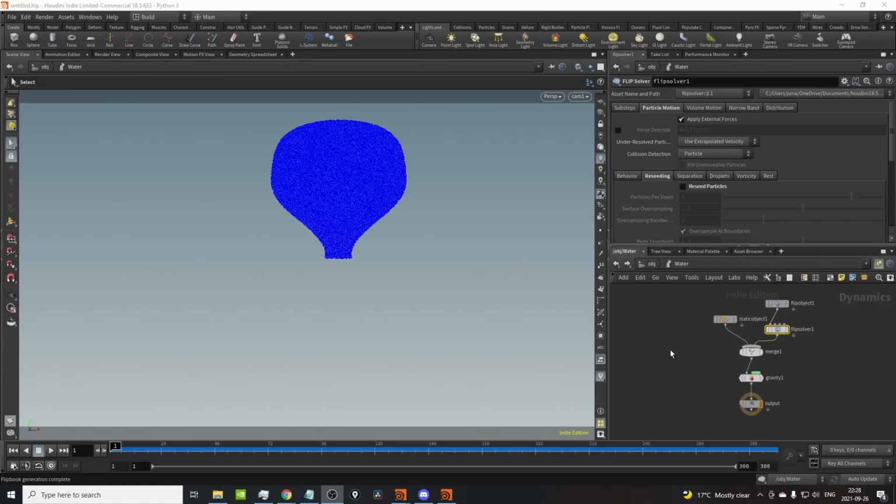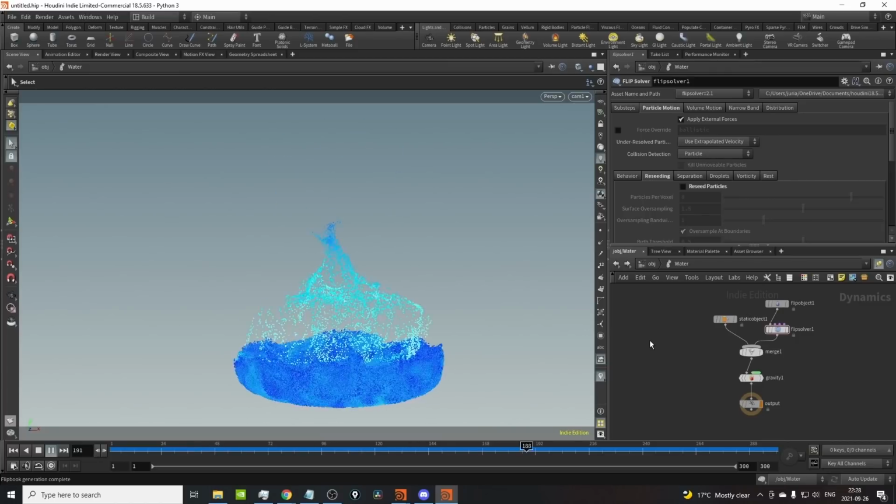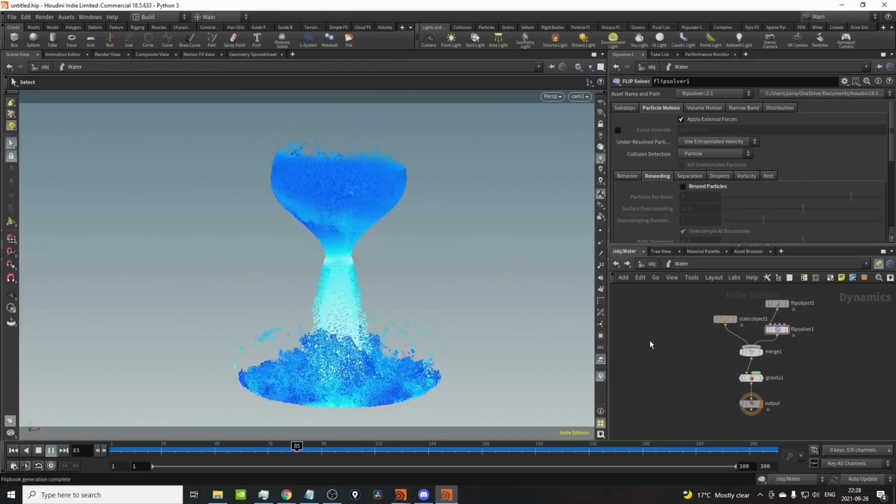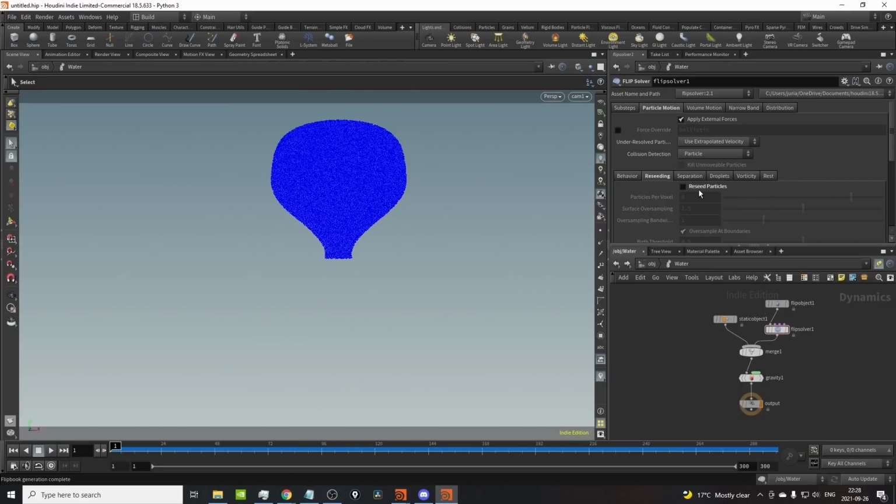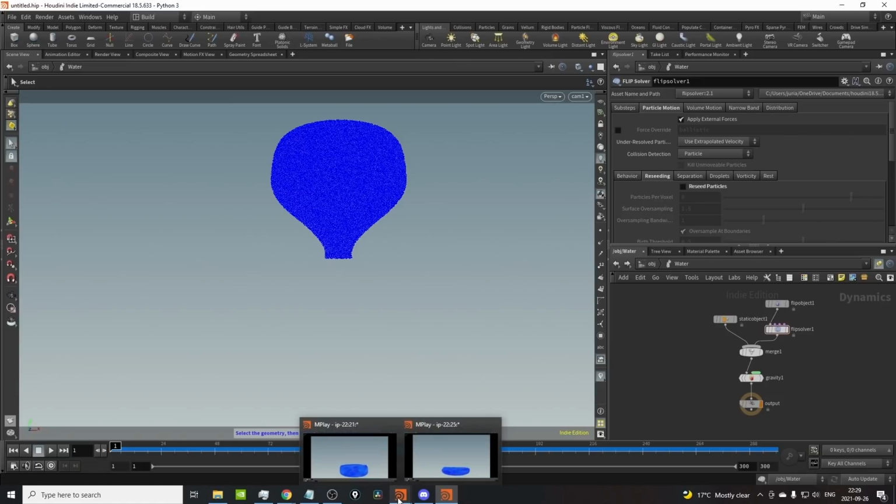Okay, so I took our simulation and I ran it through a few times just to look at what we get from it. And this is the result with turning receding off. Now by default, Houdini always comes in with receding turned on, because a lot of the open ocean toolsets use receding very, very heavily, and it can add some nice things to your simulation. But as we saw in the Divergence class, it does create a little bit more particles when you don't always want that.